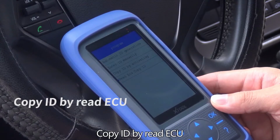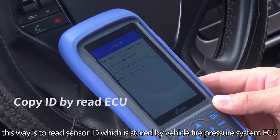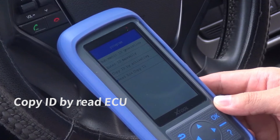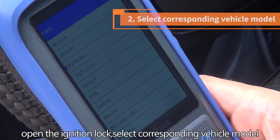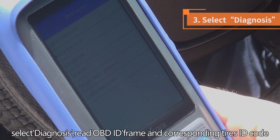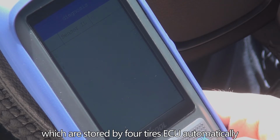Copy ID by read ECU. This way is to read the sensor ID which is stored by the vehicle tire pressure system ECU and program the ID into the TS100 sensor. Connect to the vehicle's OBD interface via wire. Open the ignition lock. Select the corresponding vehicle model. Select Diagnosis, and read the OBD ID frame and the corresponding tire ID codes which are stored by the 4 tires' ECU automatically.